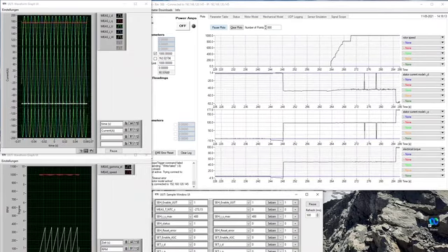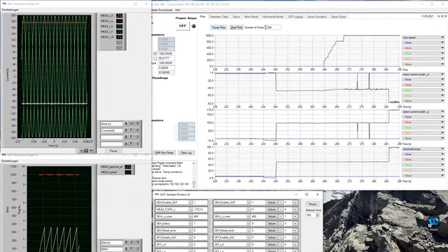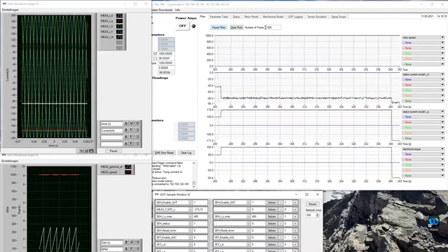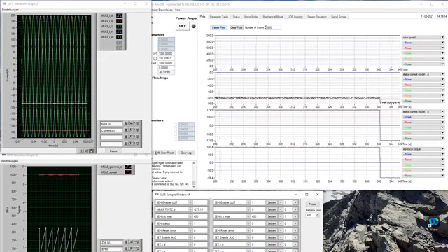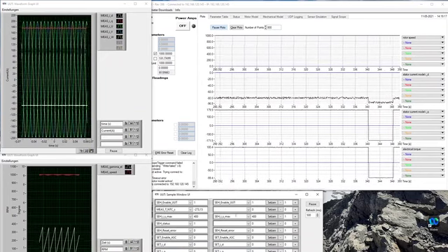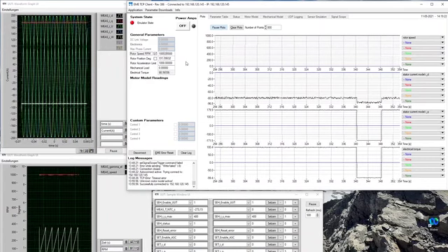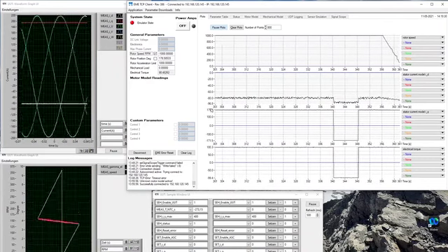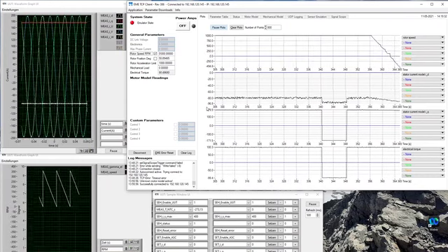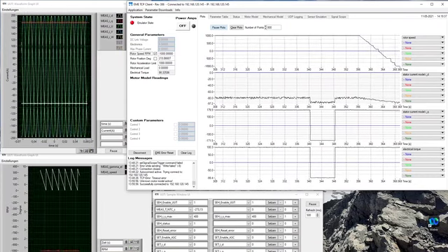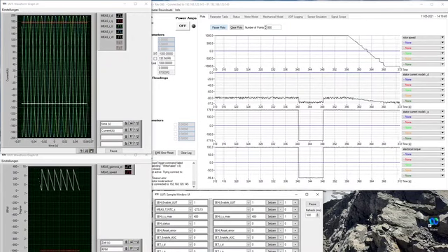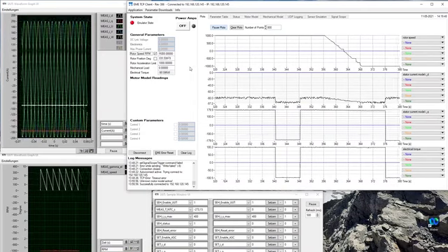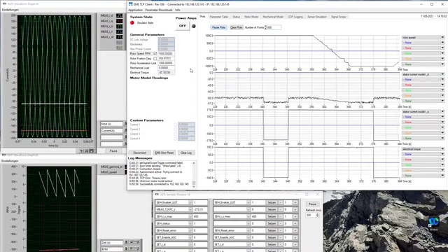The torque set point is set to 100 Newton meter and the actual electrical torque follows its set point immediately. In order to show the four-quadrant operation of the torque controller, the torque set point is changed from 100 Newton meter to minus 100 Newton meter, and the rotor speed is changed from 1000 RPM to minus 1000 RPM and back again to 1000 RPM. It can be seen that the inverter controller operates as expected in the low voltage HIL system.